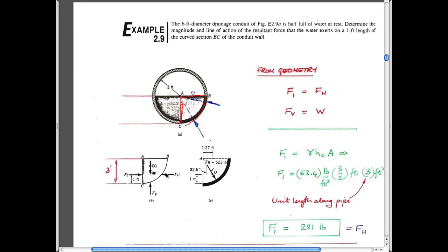And the horizontal resultant force, the only component that acts horizontally, is going to be the pressure that acts on this side here. We know that the pressure distribution will look like this. We know that it intersects the surface. And so we know that this height here is going to be 2/3 of the depth, the radius, I guess, in this particular case, which is equal to 2 feet. I said we'd never do anything in English units, but I lied, I guess. Doesn't matter. So if we want to get that, we can calculate the center of pressure, the centroid of the plate.